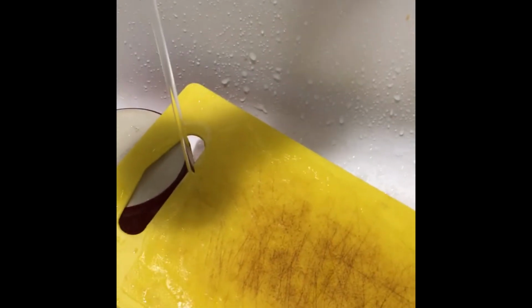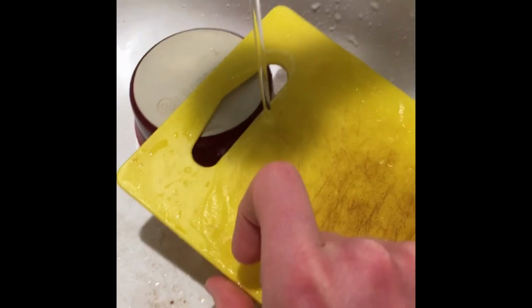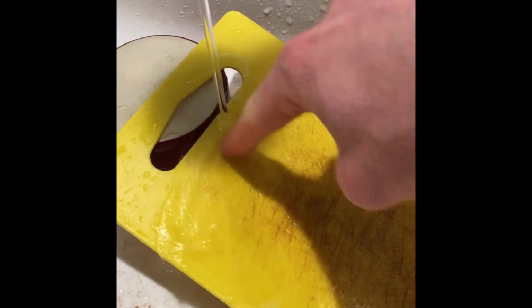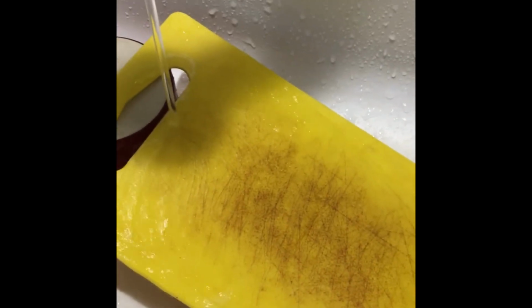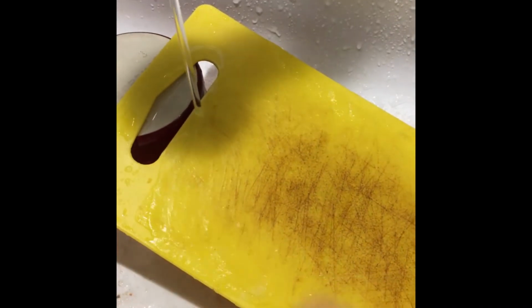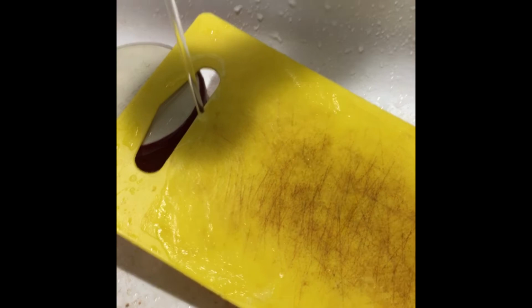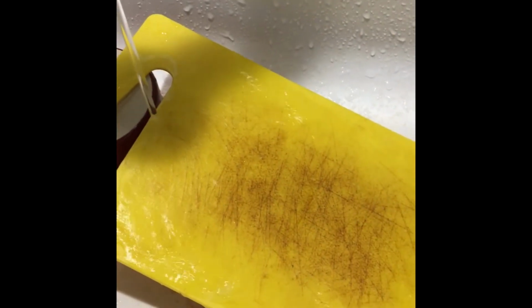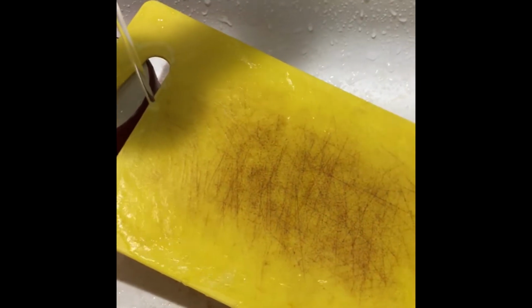And you can imagine the degree to which blood is oxygenated is determined by the thickness of the film and also the time that the film spends in contact with the air as it moves down. So we might ask ourselves, how thick is this film, as a function of how much flow rate we have going down, how much time, what is the velocity at the top, and also maybe what is the shear stress that the blood is encountering when it undergoes this process.